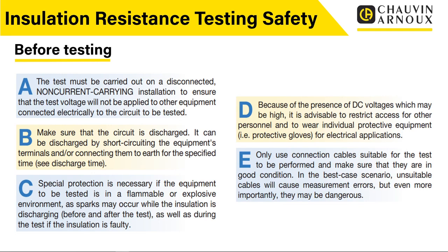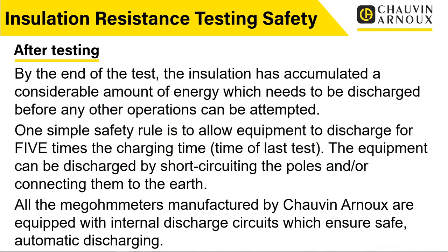But always remember, with insulation resistance testing, you are applying dangerous voltages. Therefore, you need to carry out your safe way of working. You need to carry out a risk assessment. You need to adhere to your company's policies before you carry these things out. So it is very, very important, and I can't emphasize that enough. So let's have a look at the precautions after testing.